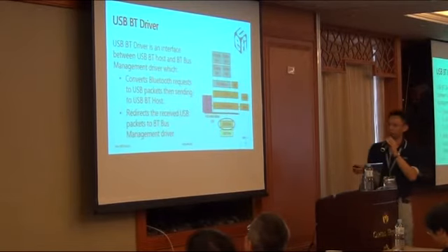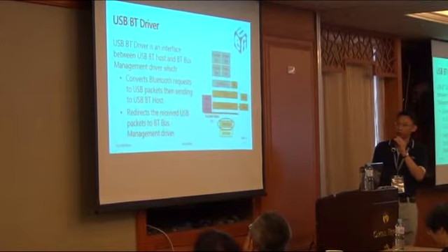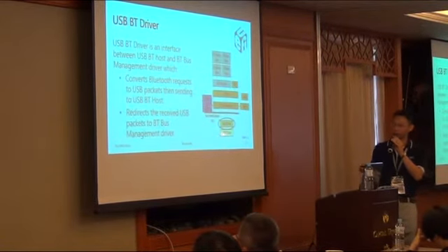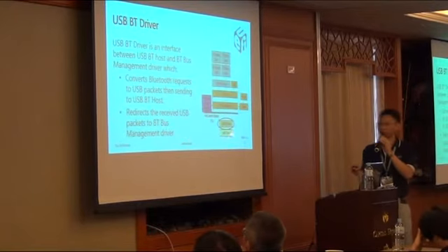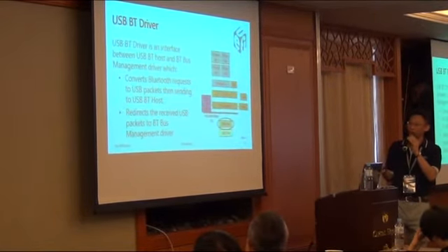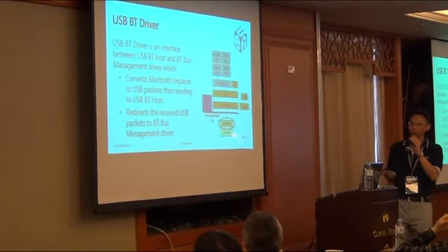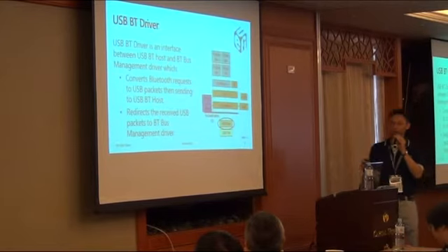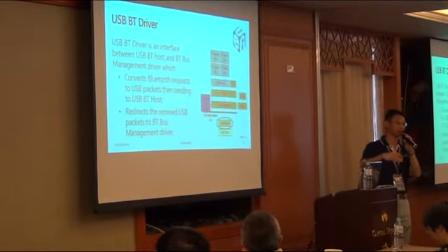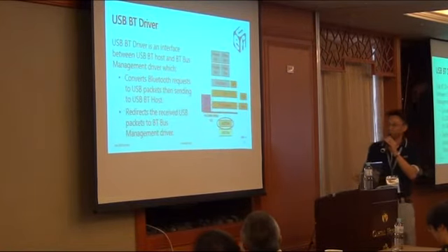From here starts the software layer implementation. As the target implementation uses a USB interface, first we need to create a USB driver to manage the Bluetooth traffic. It will redirect the traffic between Bluetooth and USB. You will encapsulate the Bluetooth packet into a USB packet and send it to the Bluetooth host to do the Bluetooth transfer.